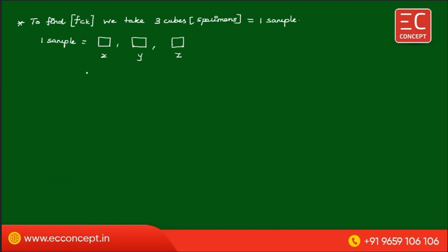Now, compressive strength of sample, be careful, is equal to average of specimen strength, X plus Y plus Z divided by 3. That is a sample.